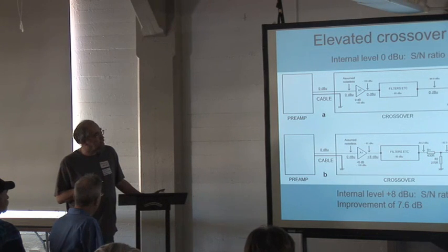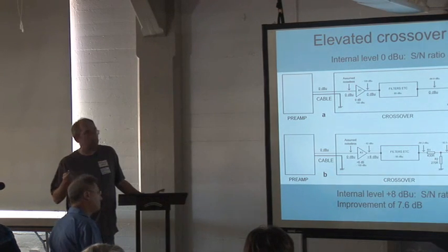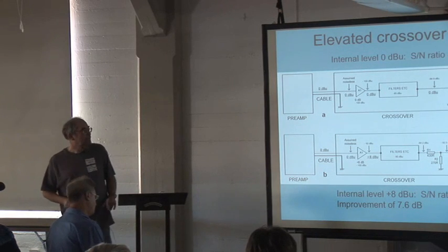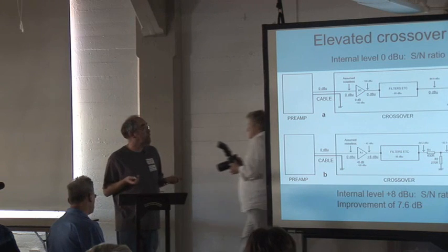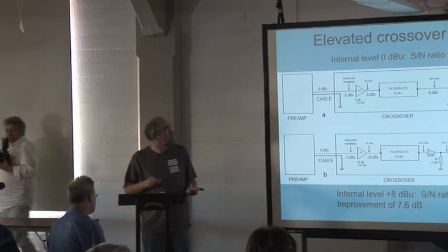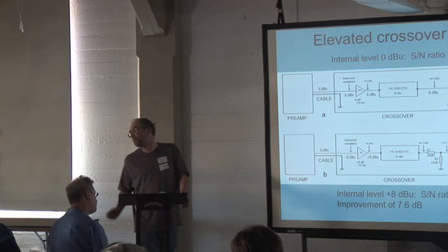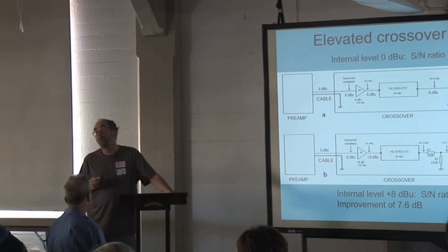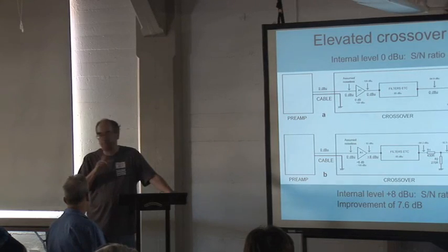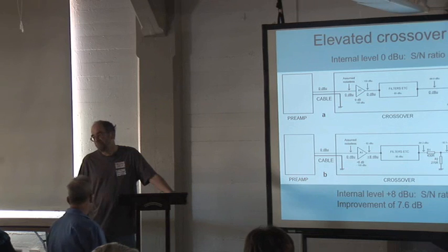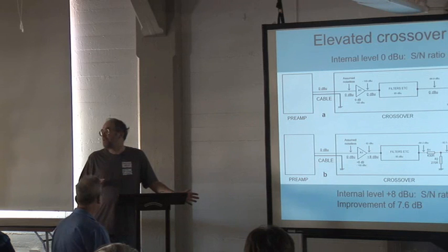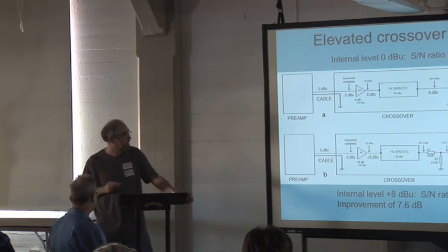Putting it in the amplifier has the extra advantage that you equally attenuate any noise that's picked up on the cable. Any ground noise in the earth, anything like that, is equally attenuated. But as I say, it means you've got a specialized power amplifier that you really cannot use for anything else. It'll have a very low input impedance, for one thing. You could put the cable connector on the amp end. Yes, indeed, a specialized cable. And this you will find is my solution in the book. In fact, I'm slightly ahead of you. It's a very good point. Yes, a specialized cable is fine. A specialized power amplifier is not a viable product. Okay, next.